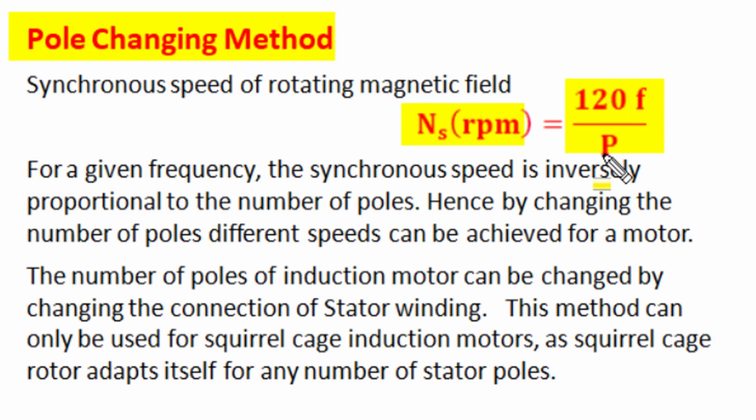When the pole number is increased, the synchronous speed gets a stepped reduction, and for the same amount of slip to produce the same amount of torque, we can have a reduced operating speed of the squirrel cage induction motor.